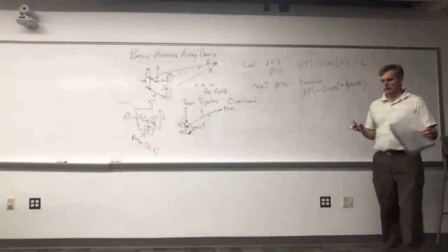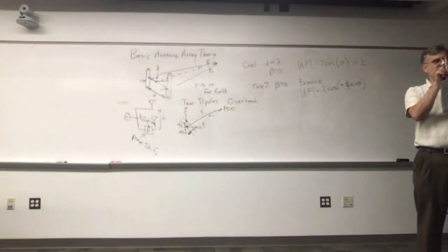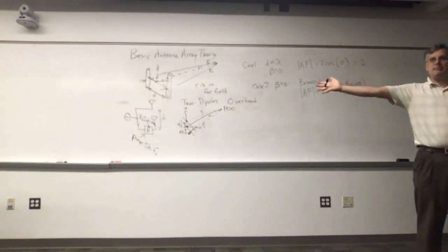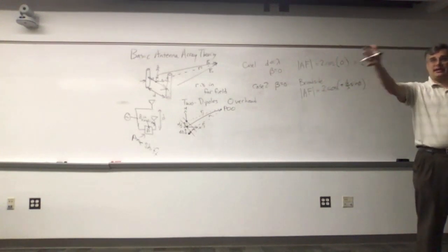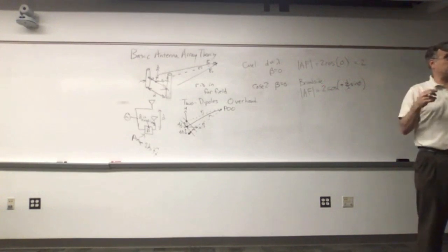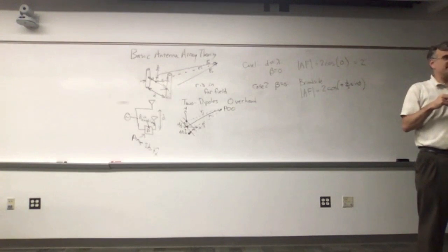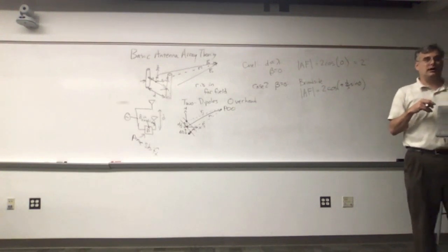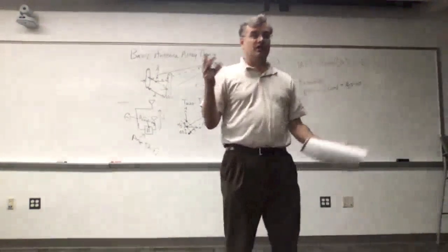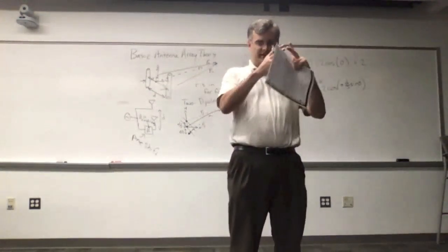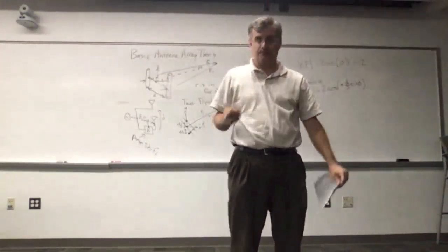If D is small, less than a wavelength, then what happens is that as I move these things apart, my beam starts shrinking, my beam width. My gain goes up a little bit, and my beam width shrinks a little bit. Standard antenna principles, right? Just because these are arrays doesn't mean that the Fourier transform relationship between current distributions and patterns isn't satisfied. I take my currents and I push them apart, I get a squinted up beam.